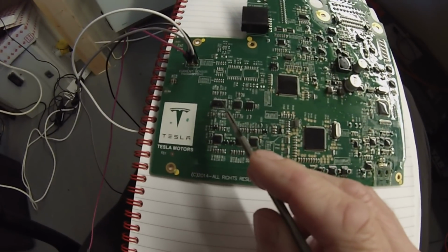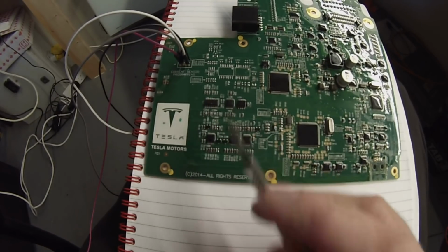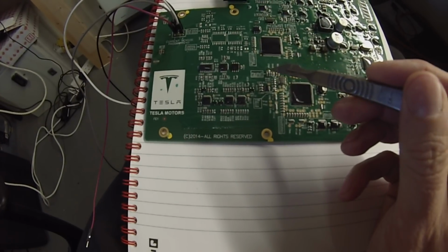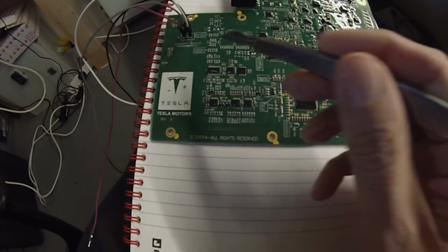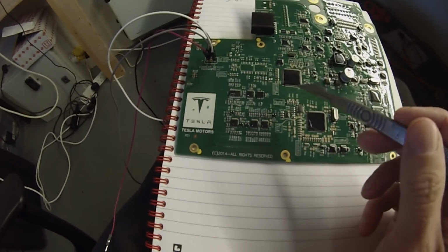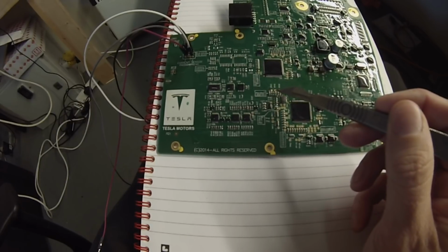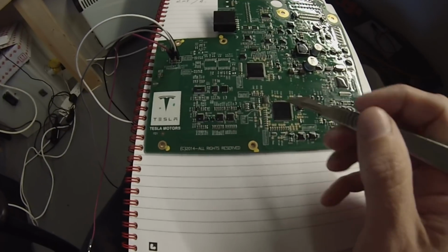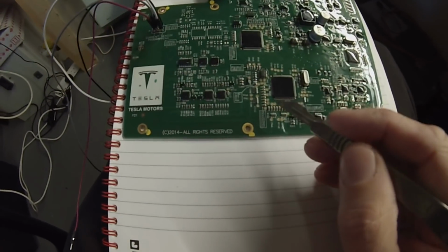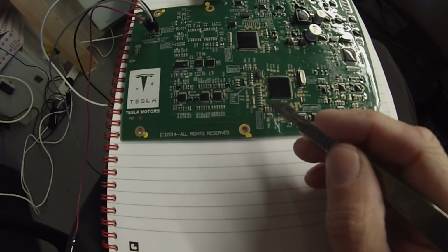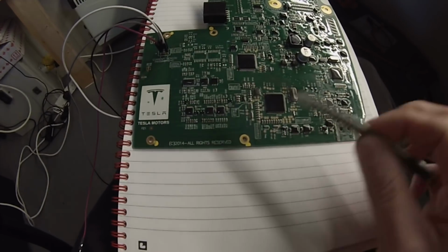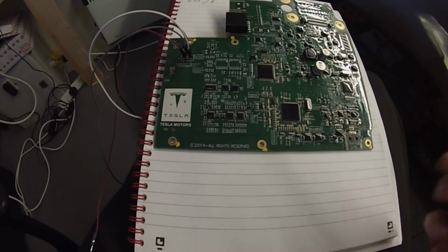So we use the very same analog overcurrent detection system. Tesla have set their trip points at 0.1 volts and 4.9 volts on the current sensor to trip TP43 or TP45, depending on whether it's a high or a low signal. The actual analog current values are fed in through some of these test points here into the TMS320 also. I forget exactly which, but we'll get into more detail in a later video. Right now, that tells us what Tesla do.